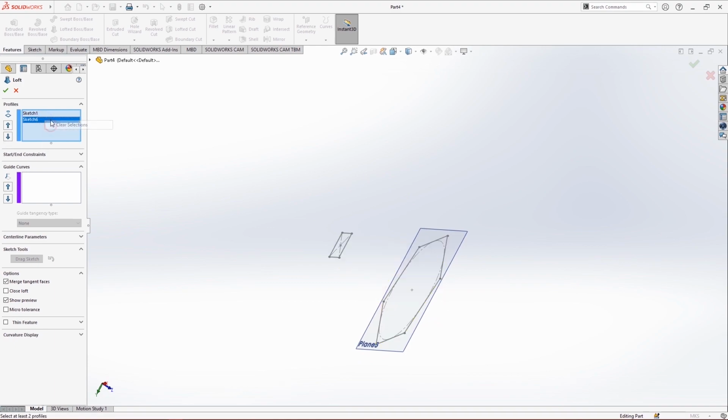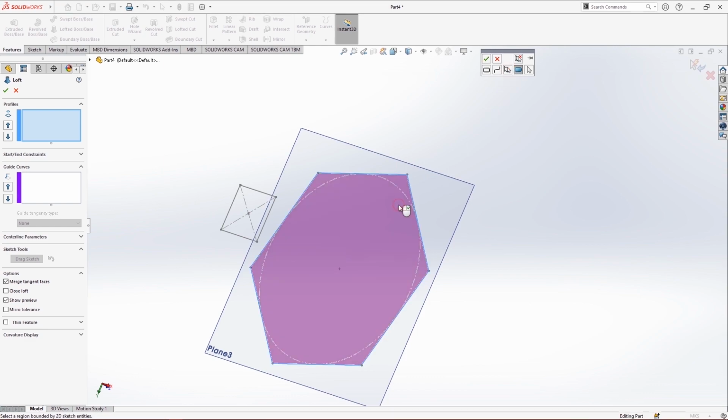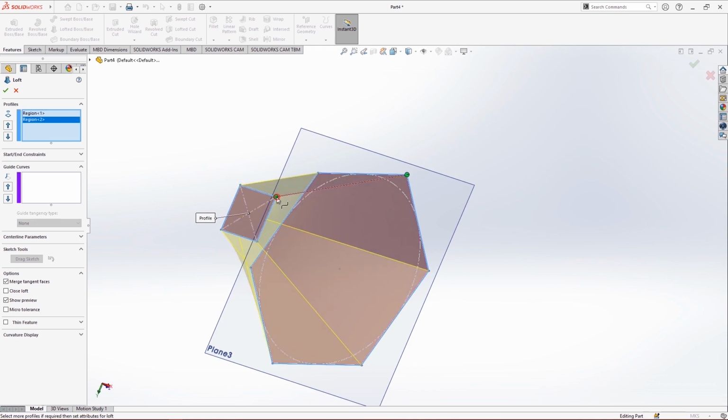Another way to do this is to right click and select selection manager. So you can select the whole sketch, closed surface, all at once, or if the sketch is actually an open loop, you can use this one, or you can use this selection manager for every single selection, or you can go for this particular surface selection. You just click here and enter, and again come here and select it, and you're done. You can mess with this one.